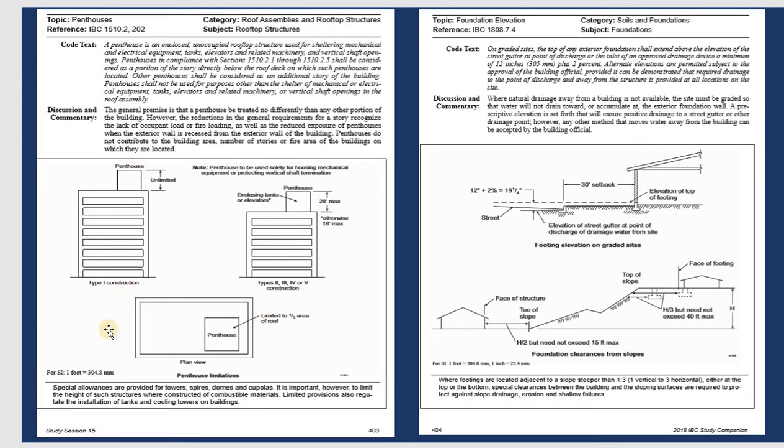And if you look at the floor plan, the penthouse should be limited to 1/3 of the area of the roof. This is the roof. So if you design a penthouse and you need to limit it, it's just less than 1/3 of the total area of the roof. That's the plan view.